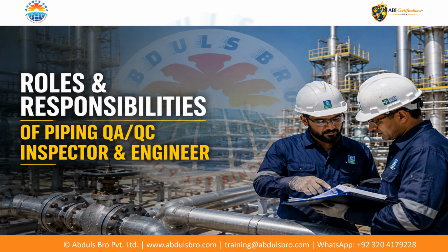Let's have a look at the roles and responsibilities of piping QA/QC inspector and engineer. Piping QA/QC responsibilities begin with understanding the applicable contract requirements, approved drawings, specifications, procedures, and inspection and test plans. Quality personnel perform inspection and surveillance throughout material receiving, fabrication, joining, installation, and testing, verifying conformity against defined acceptance criteria. They coordinate required hold, witness, and review activities, maintain objective evidence of inspection results, identify non-conforming conditions, and verify corrective action and closure before the work progresses towards mechanical completion and final acceptance.